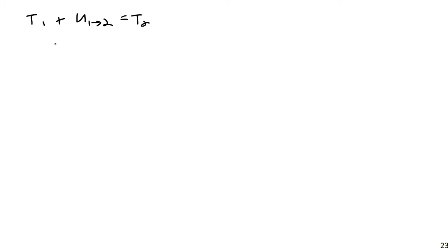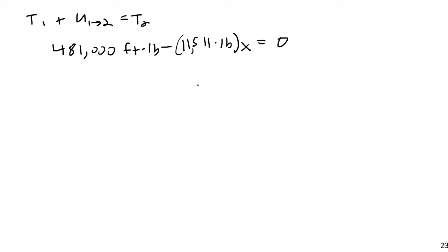So this will be 481,000 foot-pounds of energy minus 11,511 pounds times x, all of this equals 0, since the final kinetic energy is 0.